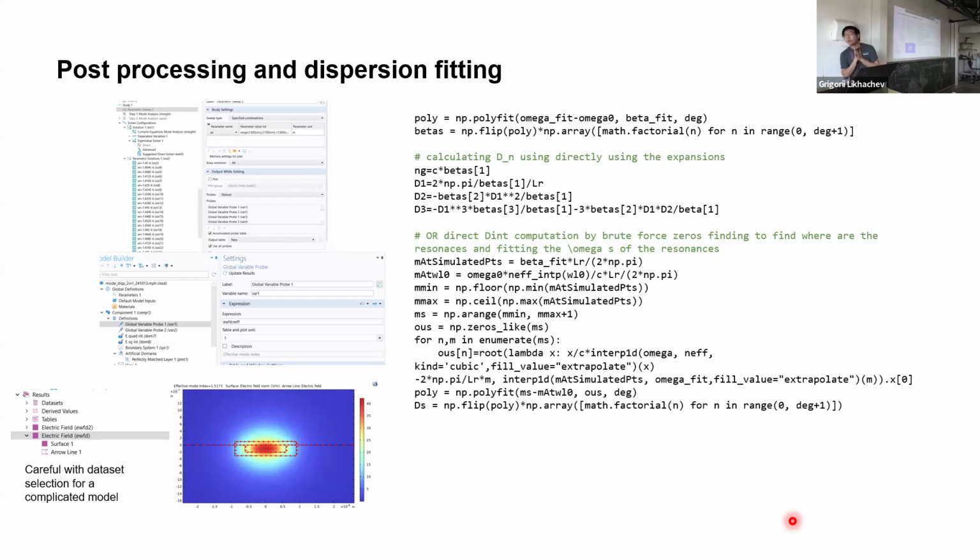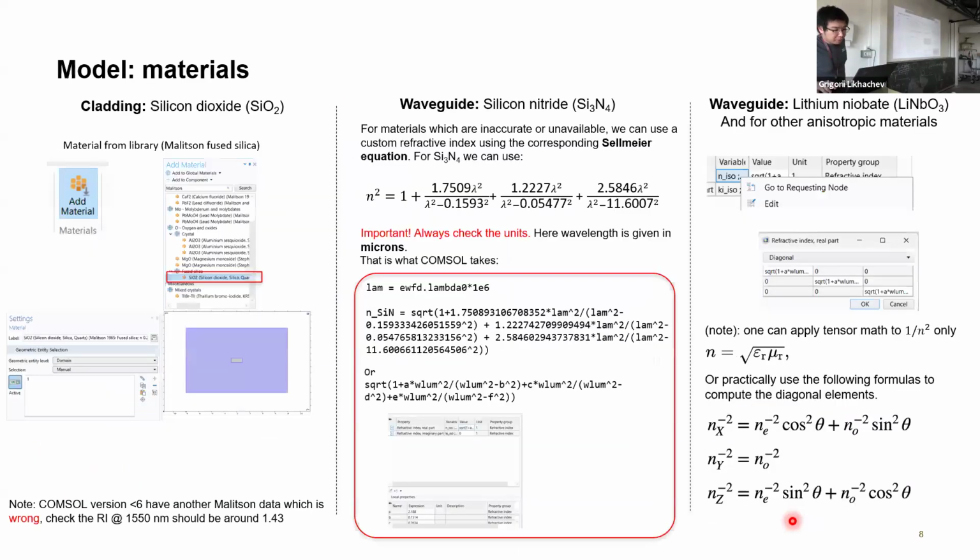Okay. So the thing is, if you go to the refractive index model, we found out... First, maybe to explain a bit, if you are not so familiar with nanofabrication, the state-of-the-art way of characterizing the refractive index of a thin film is called ellipsometry. Basically, you have a white light source with a certain polarization that is incident at an angle onto a thin film sample.